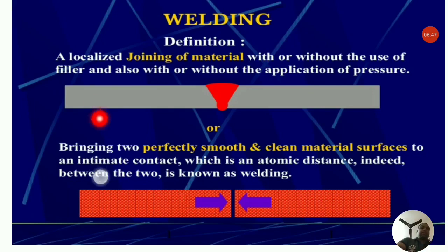Now joining obtained by bolts and screws is temporary in nature and can be disassembled whenever necessary. Now rivets are semi-permanent fastening devices, and the joint can be separated only by destroying the rivet without harming the parent materials. So this type of mechanical fastening involves making holes in mating parts, which are to be properly accounted for at the design stage.